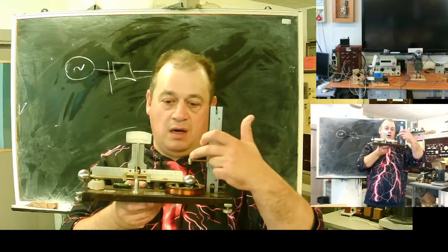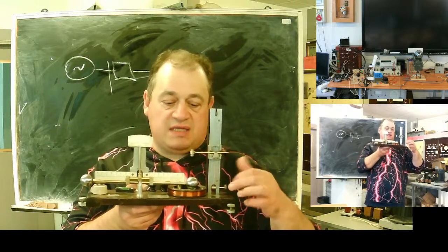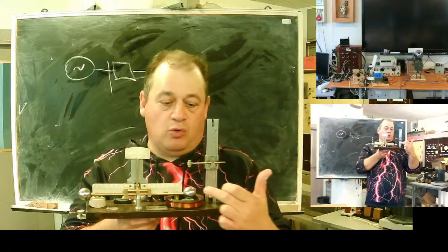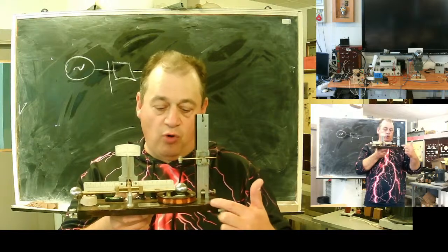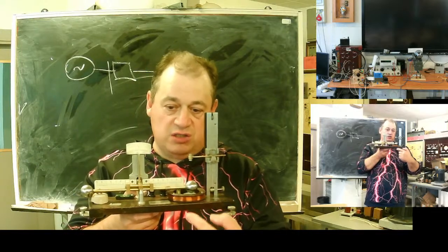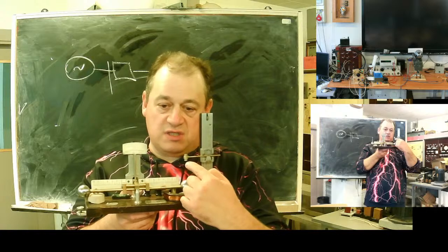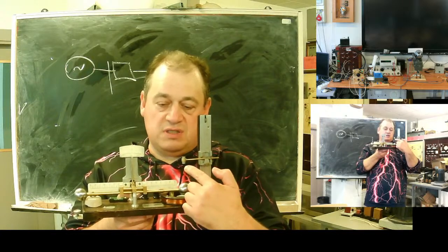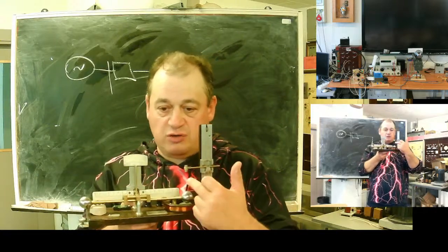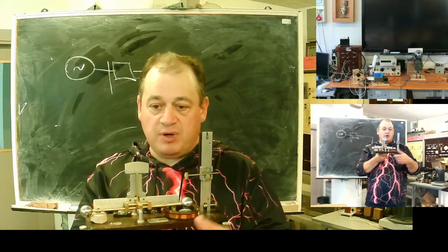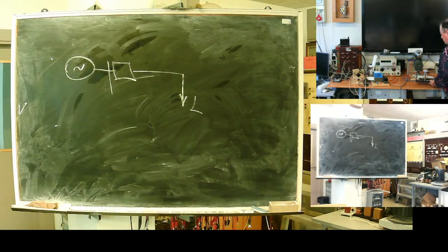Here I have a small magnet. I can move it. This magnet attracts this ball up. So the actual state of the balance is dependent on what? Of two forces. Attraction from current with coil and return force. It's the attractive force of this magnet. By positioning of the magnet, I can set what? Trip current.